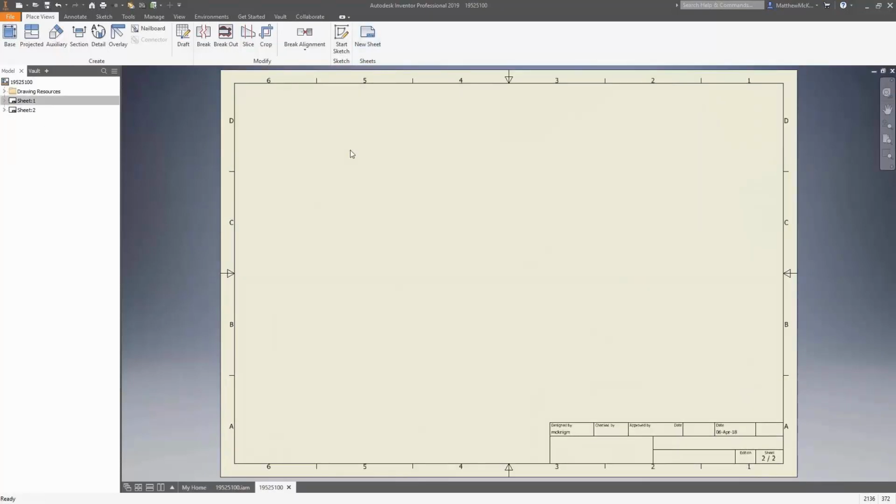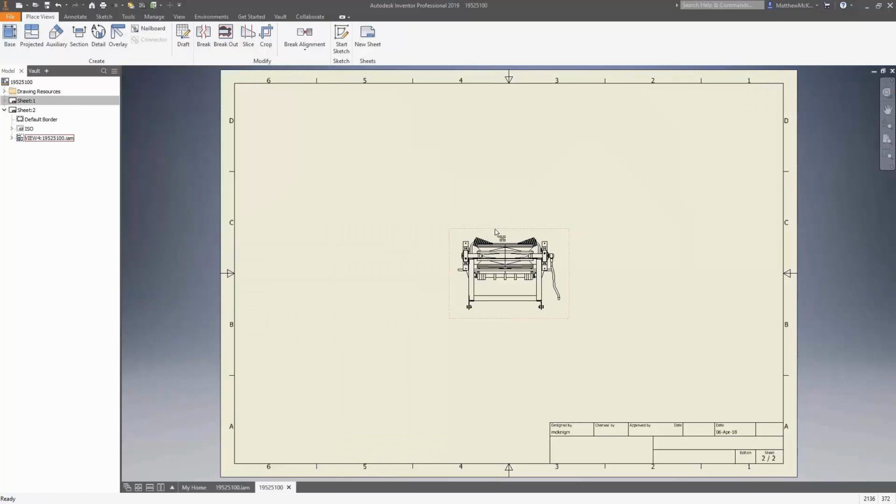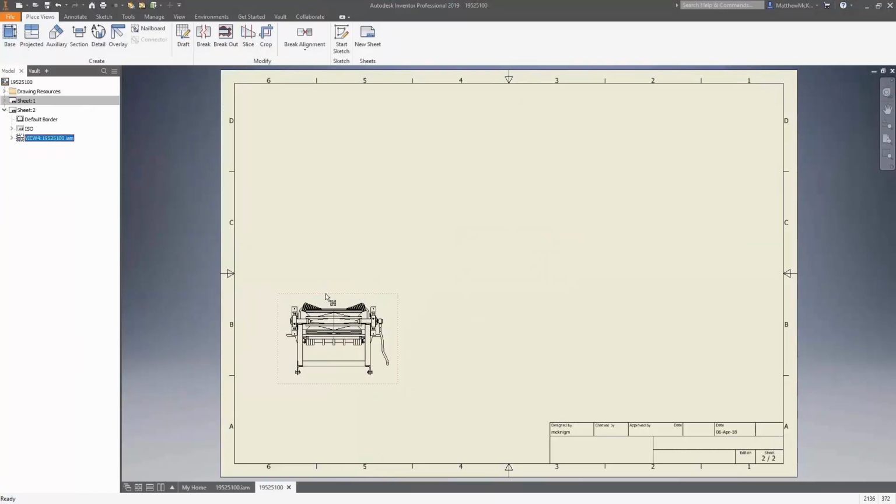Now, that might be unavoidable. You might have to do a sales drawing, and the sales drawing might need to include a specific part of the design, like the tail components that we'd previously created. So in this instance, we've created a second view. Again, only when necessary. We're creating a view on a second drawing sheet, only the view that we need. Again, if we need any secondary views from that, then we create those individually as required, rather than creating 3 views up front.